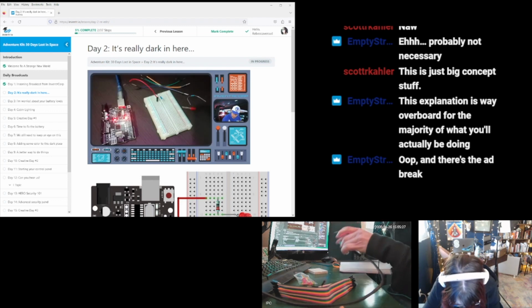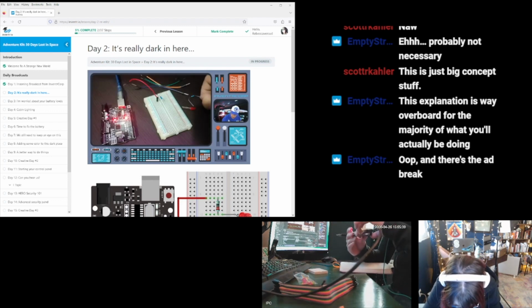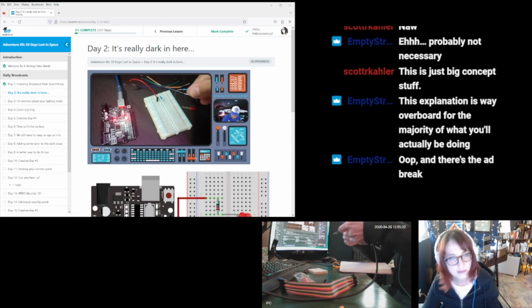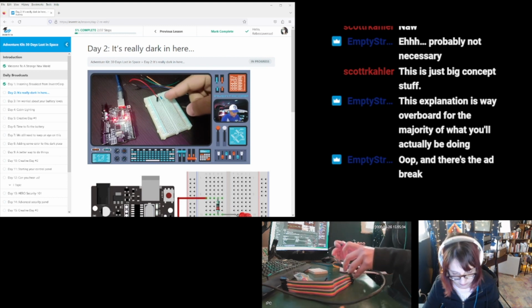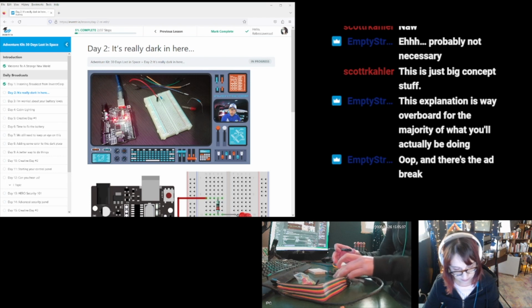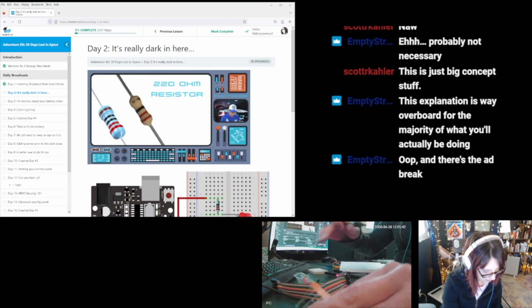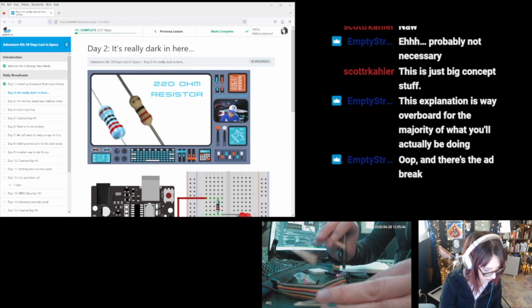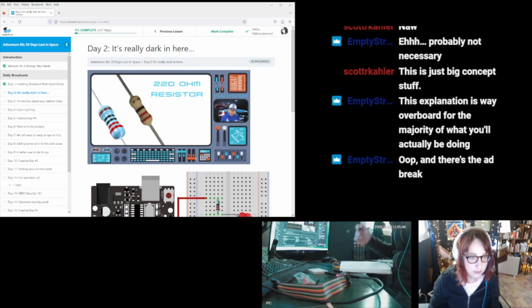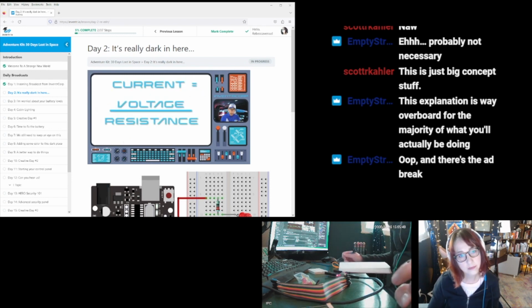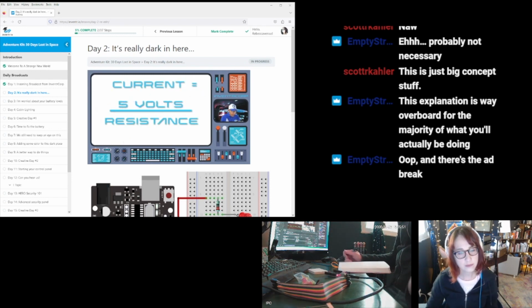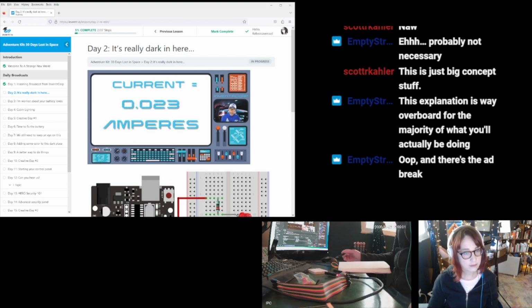We also have here some resistors like this one, or the one that's currently connected to the breadboard right here, that has a resistance of 220 ohms. So if I want to send current through this resistor using my potential of 5 volts, the current that would flow would be 5 divided by 220. So if you calculate what that value is, 5 divided by 220 is 0.023 amperes.